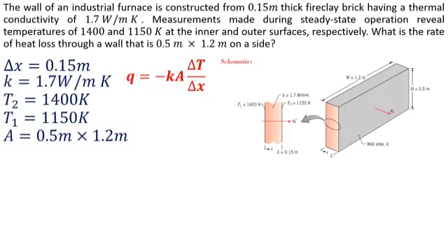And we have learned Qx double dash was heat flux, and heat flux is the heat transfer per unit area. So if we multiply the heat flux by the perpendicular area, we will find the heat transfer. So according to Fourier's law, heat transfer Q equals minus K A delta T over delta X.